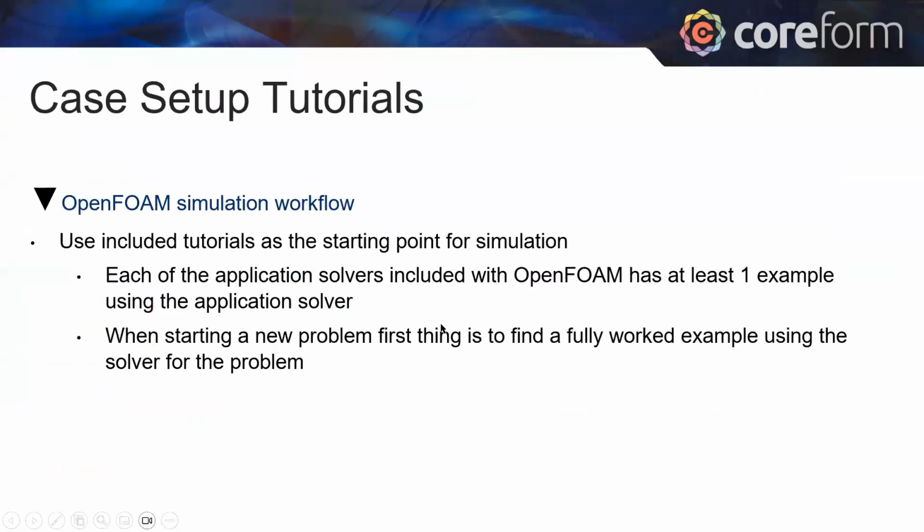Now, again, the simulation workflow. As I said, I'll use an included tutorial as a starting point for my simulations, no matter what. Like I said, there are a number of starting points or tutorials out there. Each application solver included with OpenFOAM has at least one example using it. So when I start a new problem, the first thing is to find a fully worked example that uses the solver for the problem.